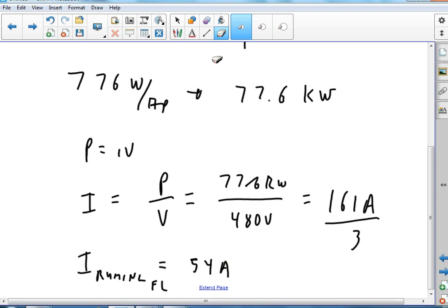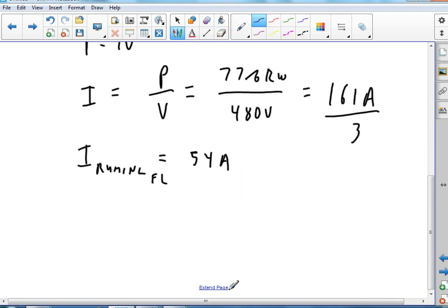Alright, so I'm sure that V is equal to IR for both of them, but I'm also sure that there's some formula for calculating it, so we'll have to find the right page again. There's the power factor page. No, we don't want power factor. Full load, no load. Okay, so current no load on page 500, 10 horsepower, 3-phase motor.